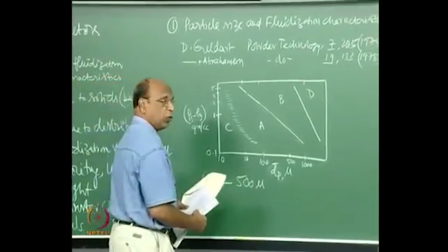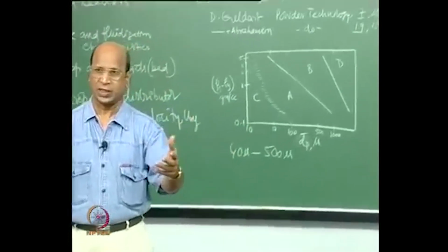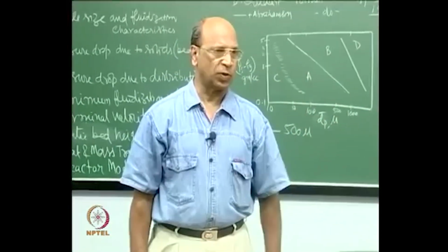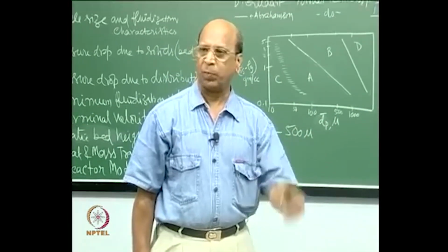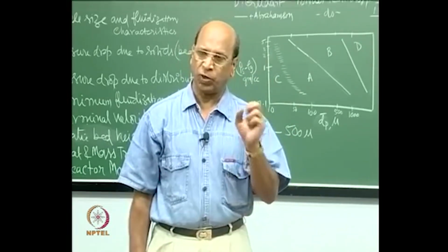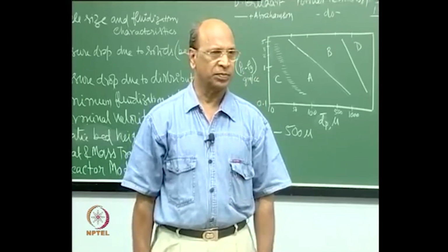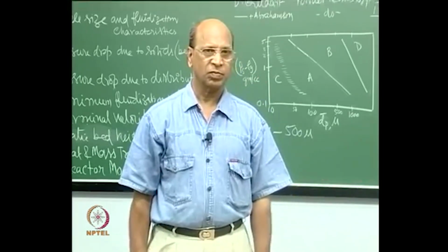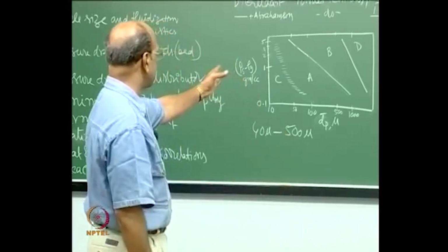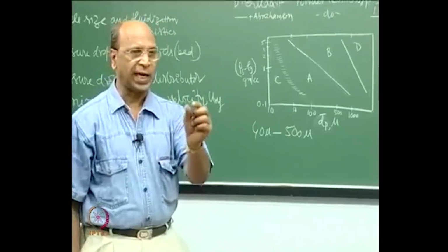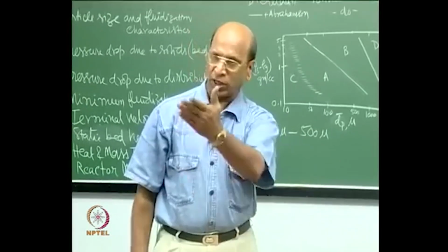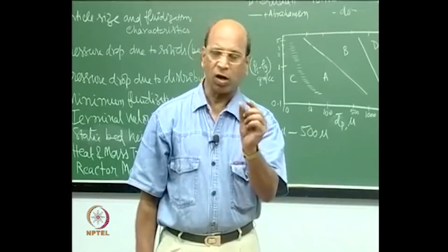For example, normally you have a process, mining for example, you took coal particles from mining for gasification, and all of them are approximately 7 mm. Will you know some idea of fluidization, what kind of fluidization you are going to get from this information? That is what we have discussed till now, right. If I have 7 mm or 8 mm, or sometimes we dry paddy here, but in other countries they also dry wheat, roasting of beans. All these are large particles.